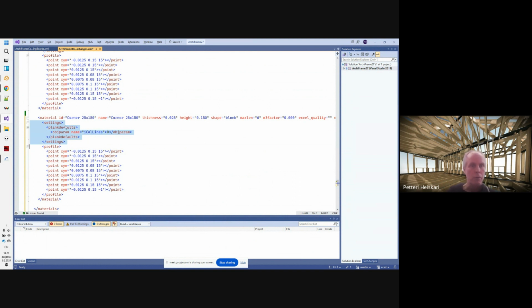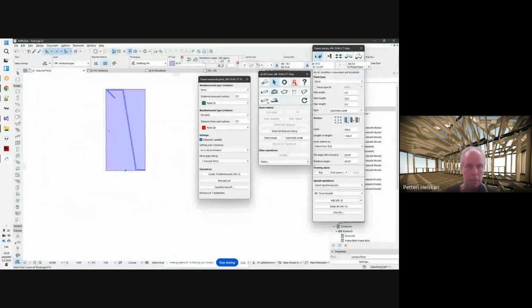So for all raw materials, you can specify settings. So you can set any ArchiFrame plank parameter. This, for example, will disable having that X symbol that you see in the column kind of pieces in floor plan. And then, yeah, before giving this a name, let's see the size. So I measure this fill, 45 by 90.